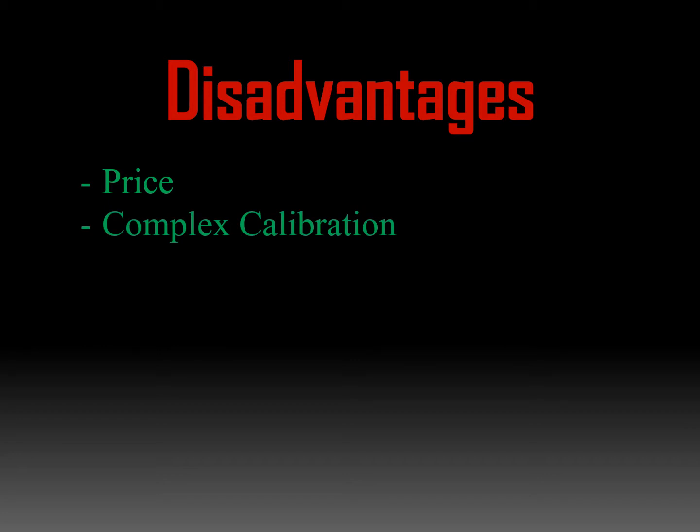The disadvantages of PAUT are as follows. Price. Equipment costs are still relatively high in comparison to conventional UT, but prices will inevitably drop with an increase in demand and growth between suppliers. Calibration complexity. A very in-depth calibration process involves adjustments of velocity, wedge delay, and sensitivity, which all have to be calibrated separately, plus time-corrected gain, TCG, to be conducted on holes at various depths.